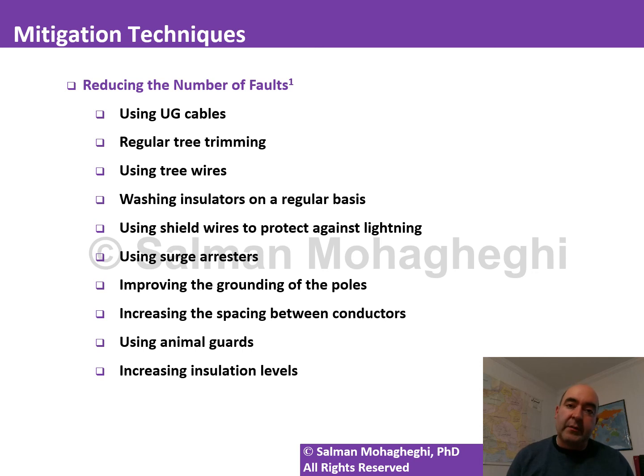So one of the things that people do, especially in forested areas, is that they trim the tree branches on a regular basis, which is quite effective in reducing the number of faults. Of course, we have to keep in mind that it has some negative environmental impacts.